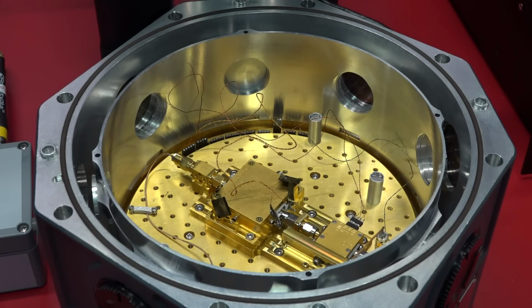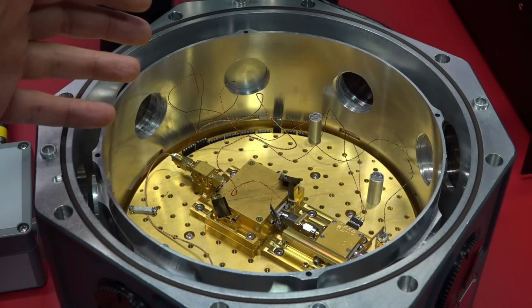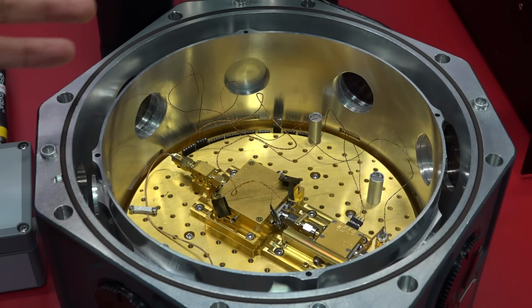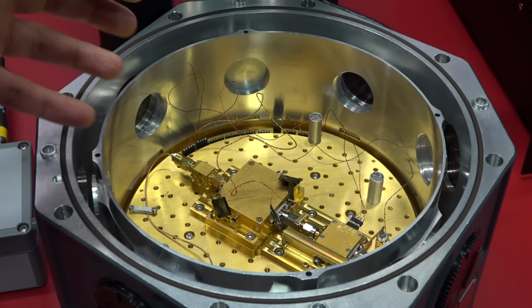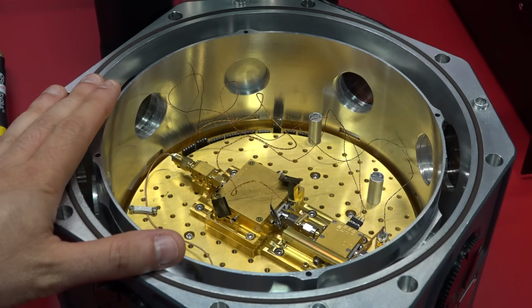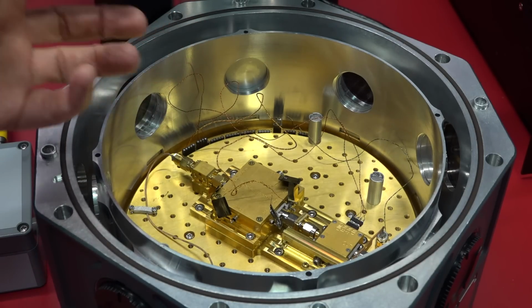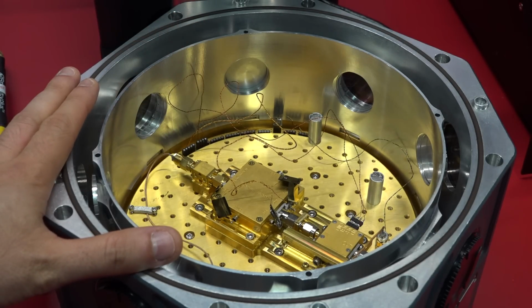Now, making noise figure measurements is already very difficult, and extracting noise parameters like gamma opt is even more difficult. But now here's another challenge. Imagine you have to do this in cryogenic temperatures. Of course, all the mechanical tuners and so on can no longer be put at those temperatures for many reasons. One is that the heat lift of these kind of coolers is already fairly limited.